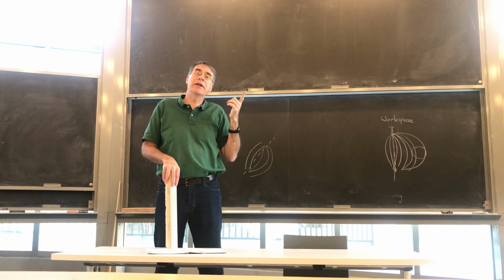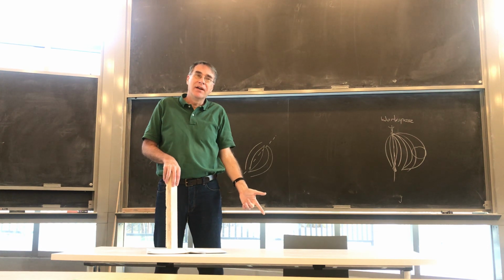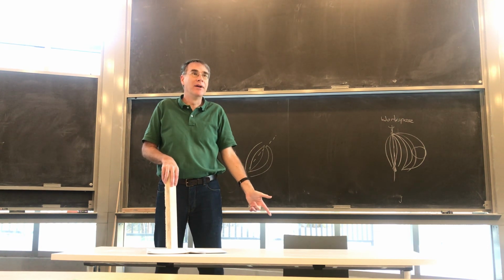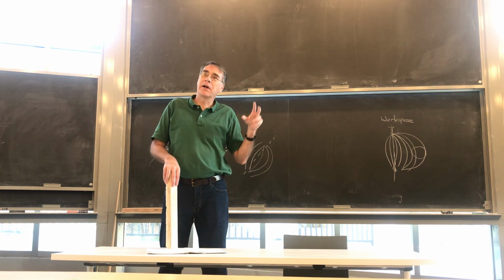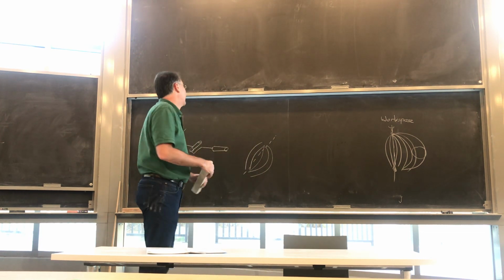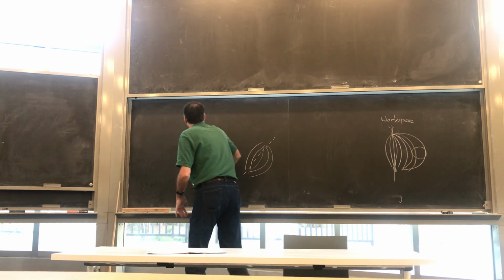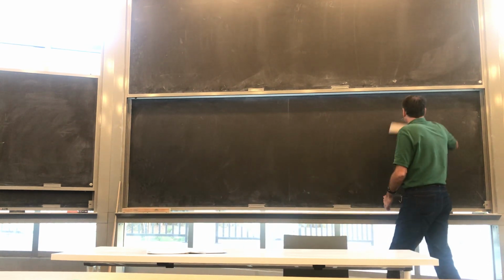Most solvers assume that you have a 6-DOF arm. If you're only going to build a 5 or a 4-DOF arm, you need to build something custom. And so we're basically going to have to write little custom solvers for our different arms. And so this is the kind of stuff that we need to get a handle on in order to be able to do the projects.